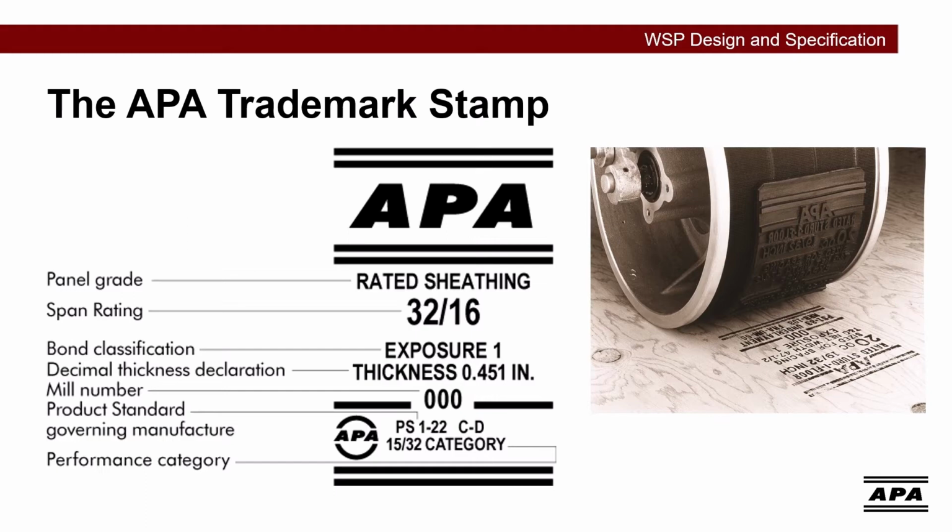Standards compliance will indicate if the panel meets PS1 or PS2. The mill number or manufacturer's code identifies the facility where the panel was produced for quality assurance and traceability. Understanding this stamp helps ensure that you're using the right panel for the right application, meeting building codes and structural performance needs.